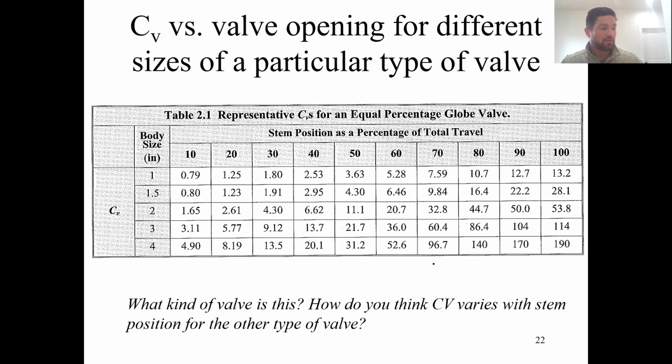Okay, so this slide shows CV as a function of valve opening for different sizes of particular valves. The first thing I want to say is that if you decide to use a linear valve, we can typically just go to these tables right here and take the value based on the body size.